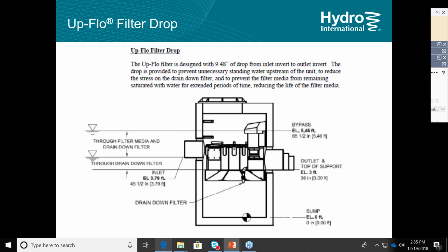So by placing the pipe at the top of the media, any flow coming into the manhole generates head directly on the media and pushes flow out of the filter bags. That's a condition that we strive for.